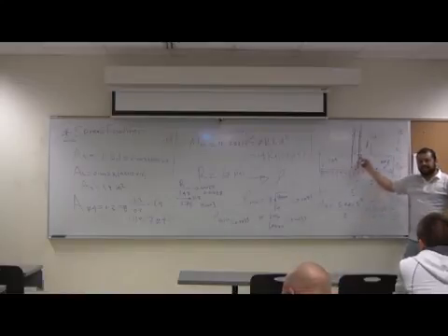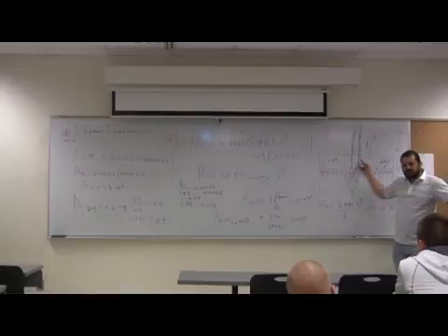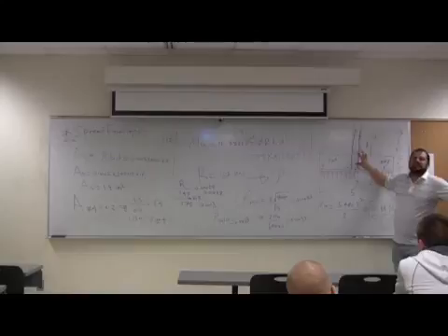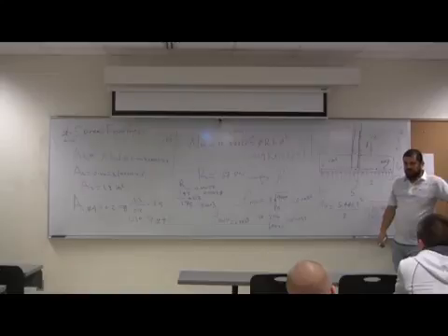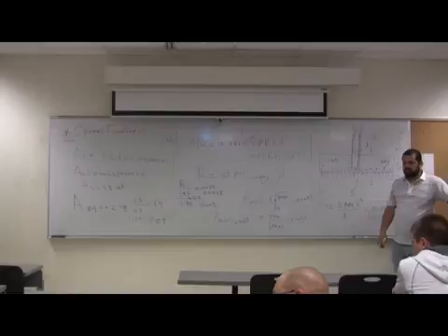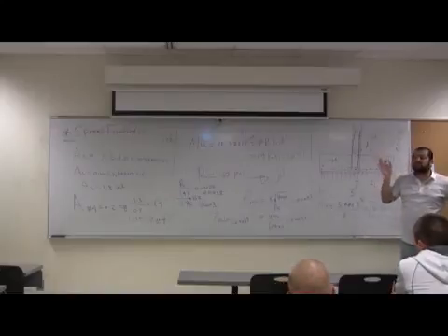Remember, is the bar in compression or in tension? The wall is a compression member, so usually you don't need 30. You need a very small length. At the top of the footing, when we tie it together, does it matter? Can we just use number 3s every time? By the way, this is for constructability.